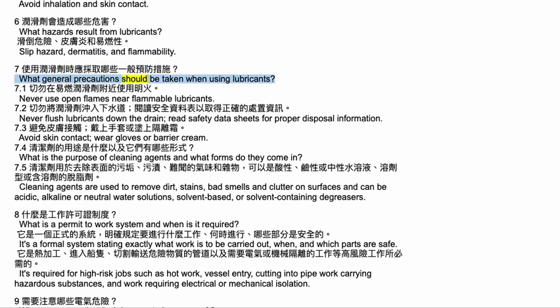What general precautions should be taken when using lubricants? 7.1 Never use open flames near flammable lubricants. 7.2 Never flush lubricants down the drain. Read safety data sheets for proper disposal information. 7.3 Avoid skin contact, wear gloves or barrier cream.